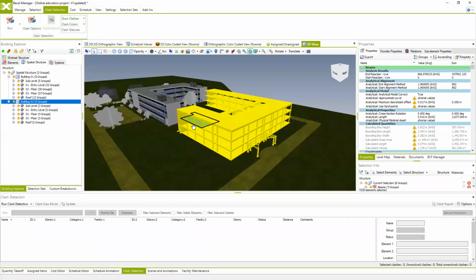This is something that frequently happens, that some design teams forget to delete or accidentally make duplicate elements. If you want to check these kinds of issues, which are brief BIM checks for duplicate elements, you can use the option to run clash detection for selected elements only or run for selection duplicates.